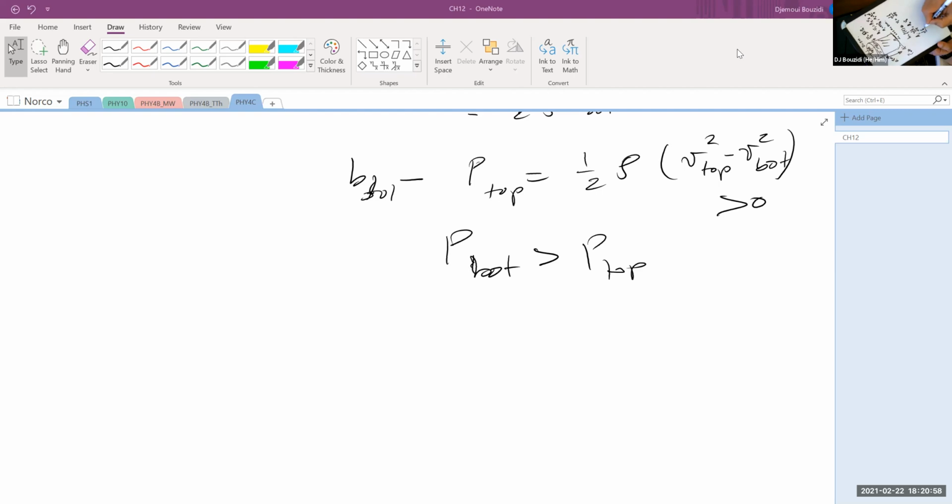So we're going to find dH over dt equals the ratio of the areas, so I'm going to write A2 over A1. This is a small number, times the square root of, what was the V2? 2 times gH. Please check my algebra in here. Plus 2 times the difference in pressures, P1 minus P2, divided by rho. So this is the expression that we have in here.